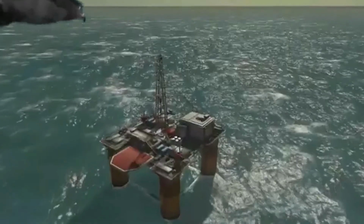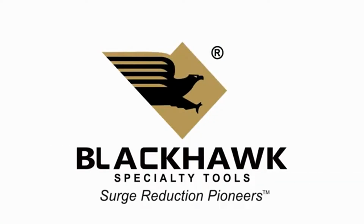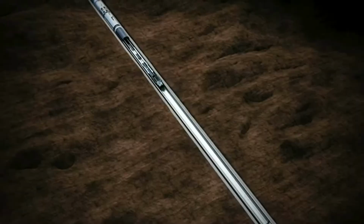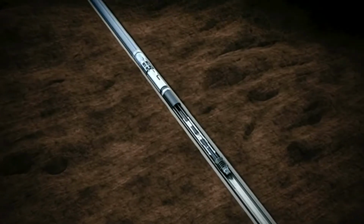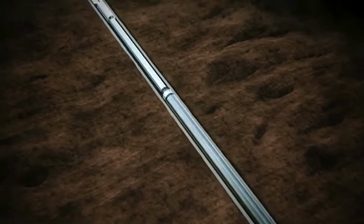When running subsea casing or liner into a wellbore, Blackhawk Specialty Tools equipment and process will provide an alternative flow path. As the liner is lowered in the wellbore, surge pressure is created by the close tolerance liner and casing combination.